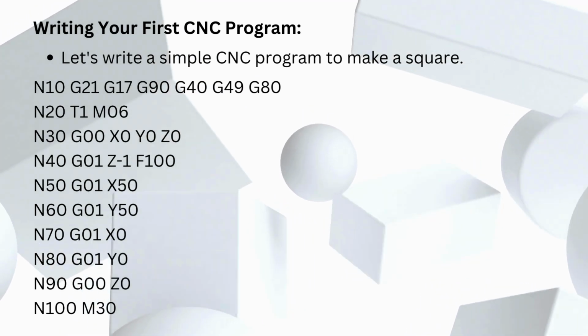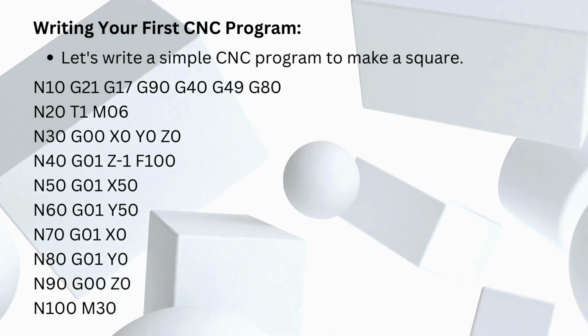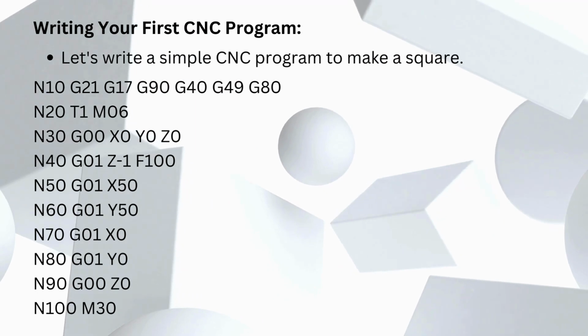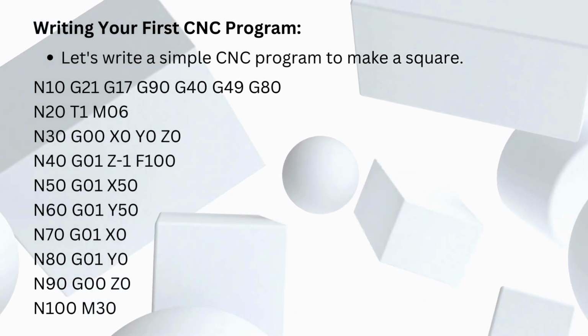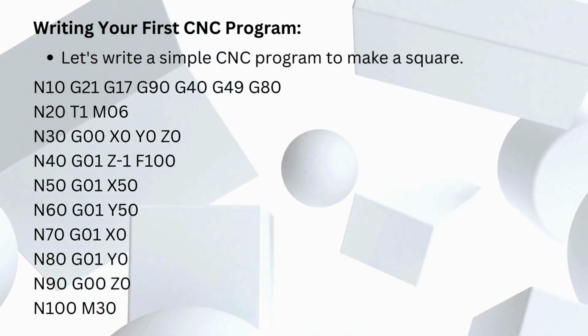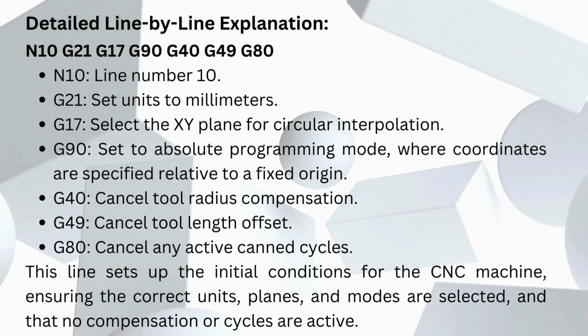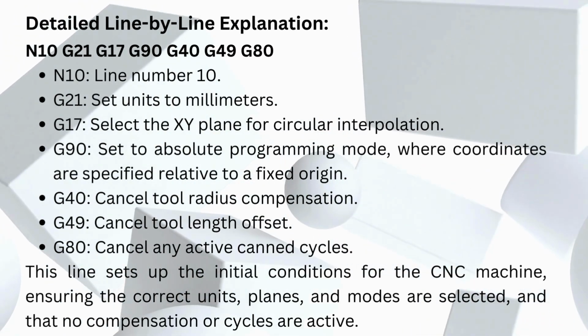N50, G01, X50. N60, G01, Y50. N70, G01, X0. N80, G01, Y0. N90, G00, Z0. N100, M30. Detailed line-by-line explanation.